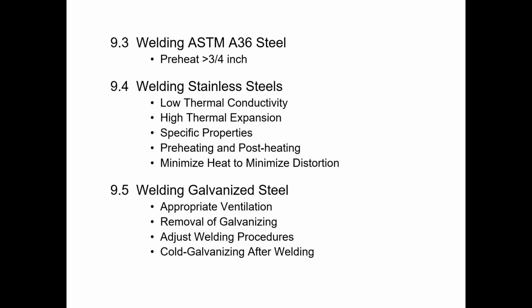And that last bullet point there, minimize heat. What that means is you're welding at a lower temperature. So you're reducing the heat of the weld process to minimize that distortion.